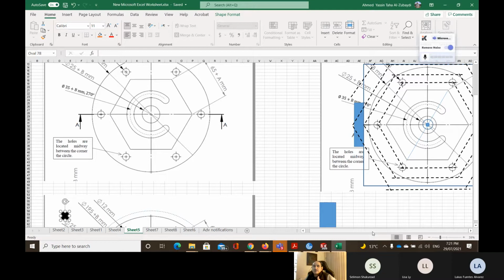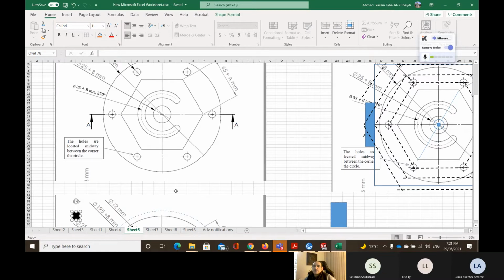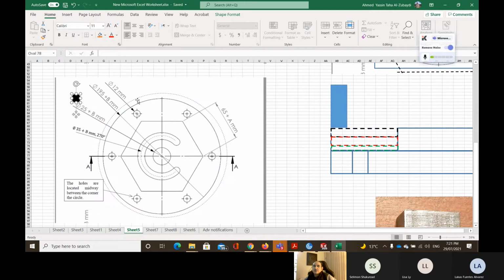Check the quality of the surface before you take it to setup number 3, which is holding the part by using the bolts and the T nuts on the table and doing the profile finishing cut at the end. Then setup number 4 is to take the part once again to the inspection table and check the dimensions and the quality before you pass it.